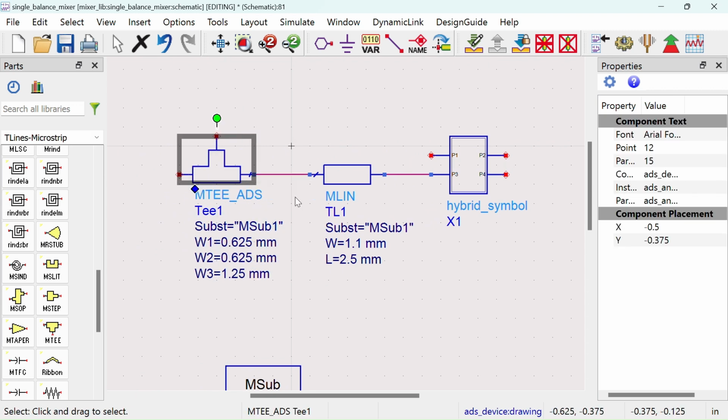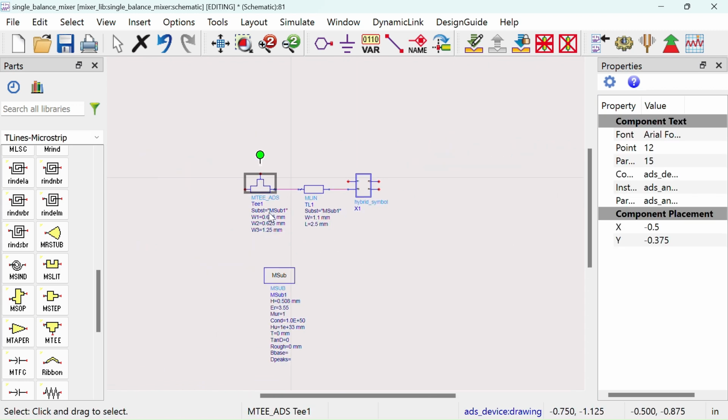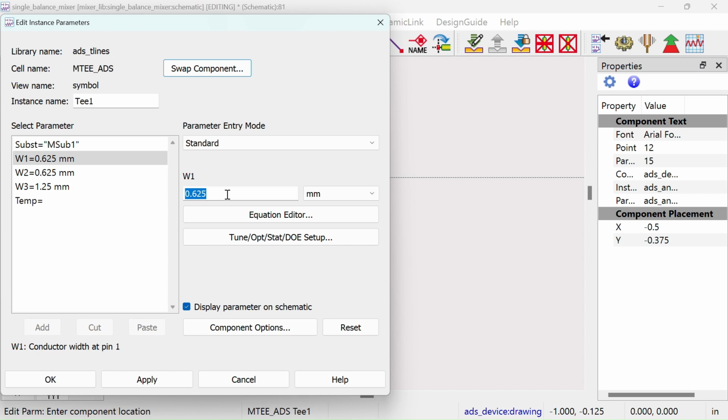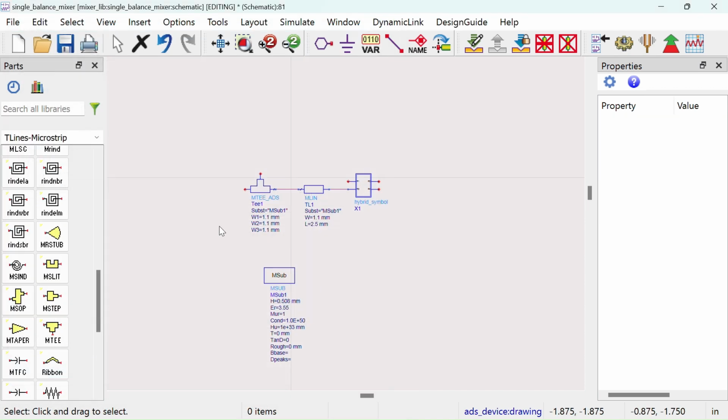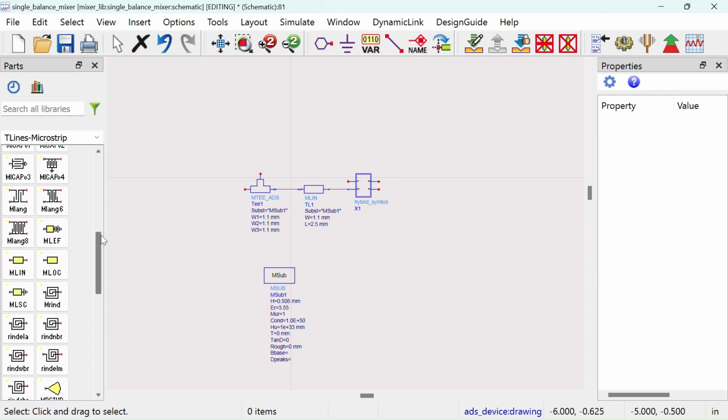Although it shares similar current voltage characteristics with a standard PN diode, the Schottky diode is based on a metal semiconductor junction rather than a PN junction. This unique structure provides several benefits, including faster response times, a lower forward voltage drop, and reduced junction capacitance, making it highly suitable for high-frequency applications.